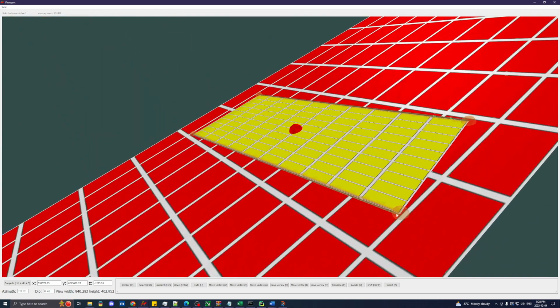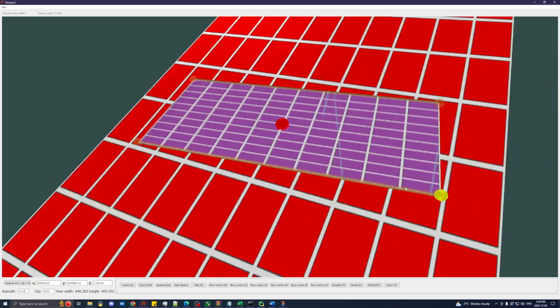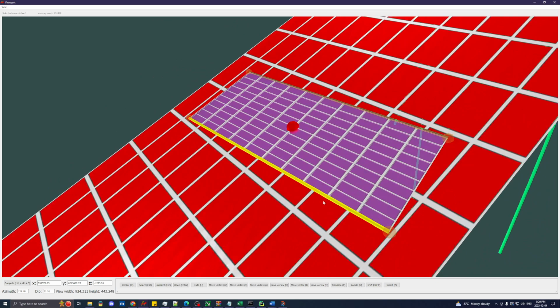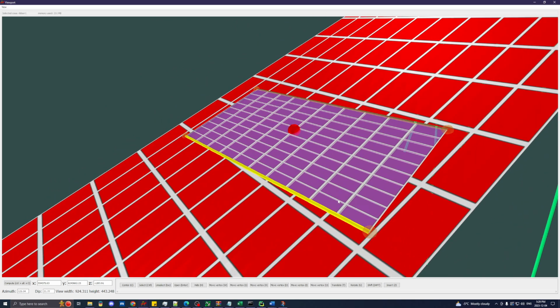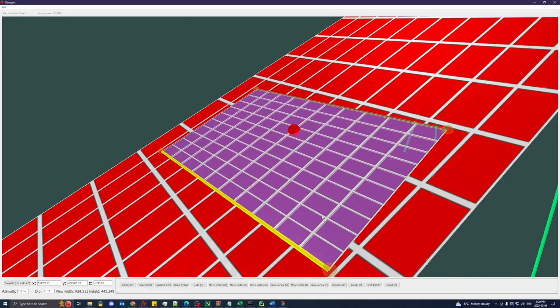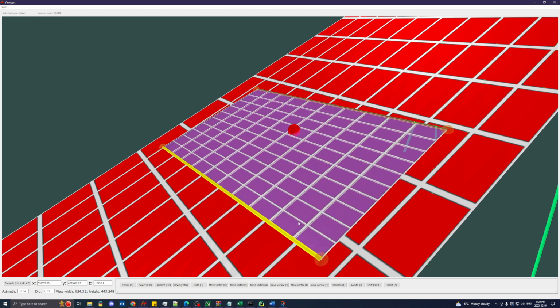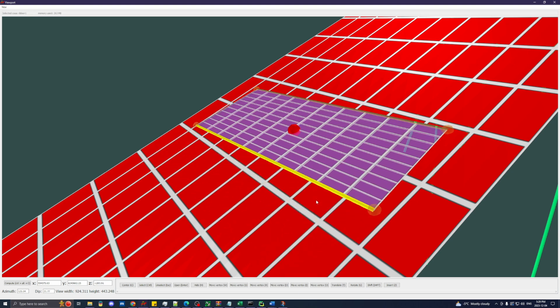And you'll note that our ribbon is now largely controlled by these control lines, which you see in orange here. So I can highlight one and right click and drag, and that will be changing this dimension of the ribbon here.